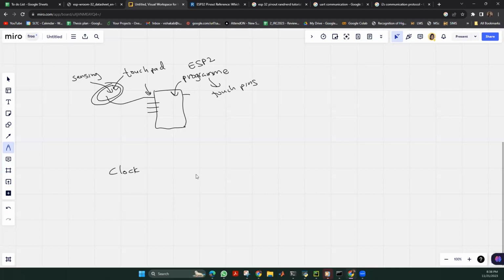If you record some audio data, you need to convert it into digital data through a certain ADC, and then transfer that data from one controller to the other controller using the I2S interface. The I2S interface takes input of digital audio data.